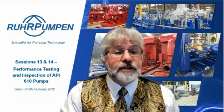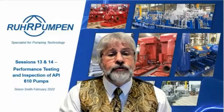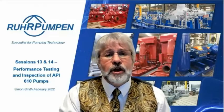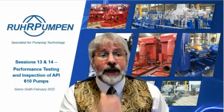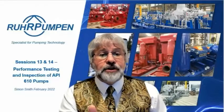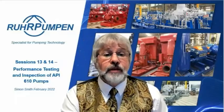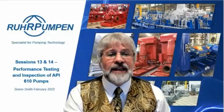Raghupati Singaraj says, mechanical run test until oil temperature is stable, versus a 4 hours mechanical run test. What advantage? Well, they're effectively the same thing. Remember, the mechanical run test until the oil temperature is stable is likely to take 4 hours. If you want it 4 hours after that, it becomes 8 hours.